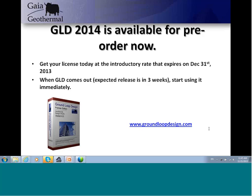When a fluid temperature reaches a certain point, the hybrid system kicks in, and that's a very reasonable way to do it. But what we're using GLD for at this point is really predicting the minimum, essentially the optimal, loop field size to give you the predicted temperatures that you want, and then, based on the hourly profile, when you expect the hybrid system to kick on, meaning the temperatures in the ground loop are going to be at a point where that hybrid system is going to kick on. You design your loop field using this tool. You think about what temperatures you want your hybrid system to come on, you size your loop field for that, and then based on the hourly data, you can figure out when the hybrid system is going to come on.